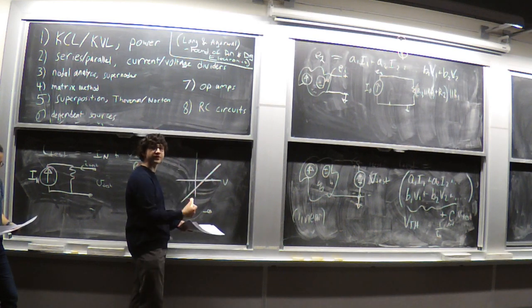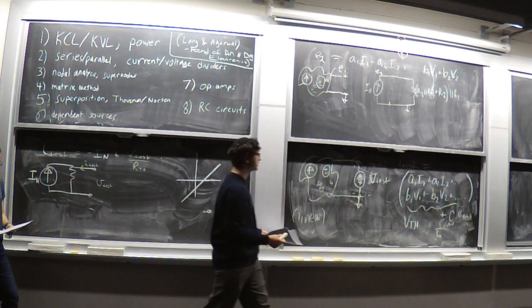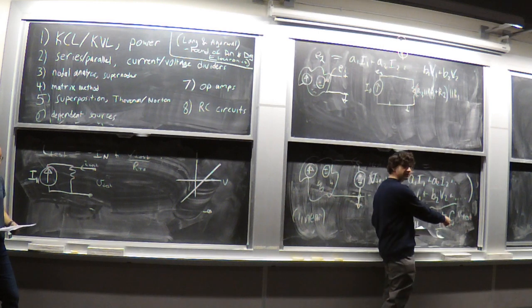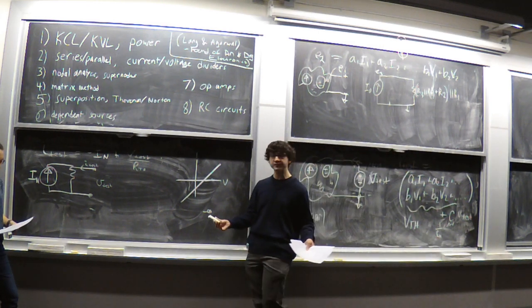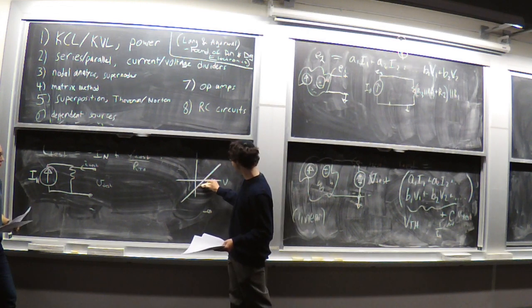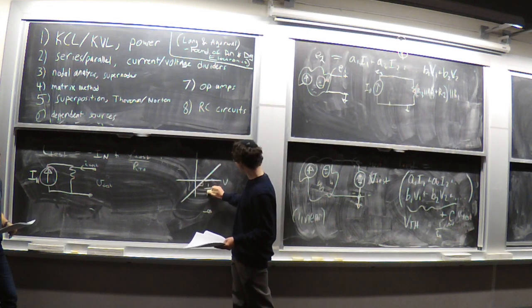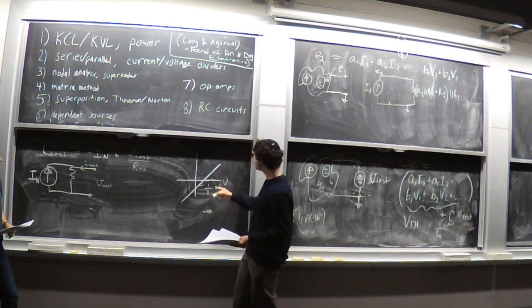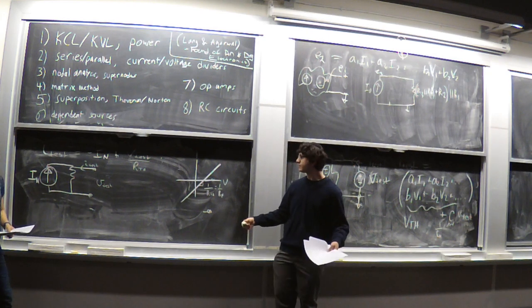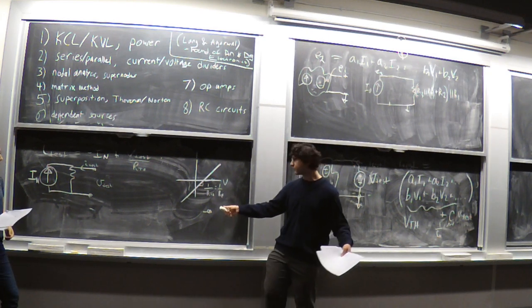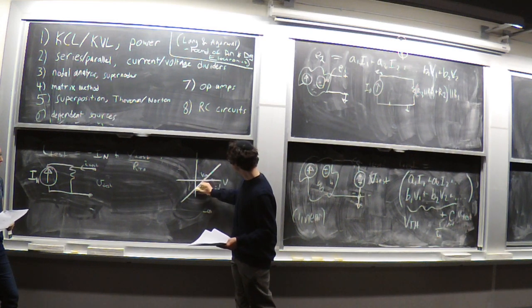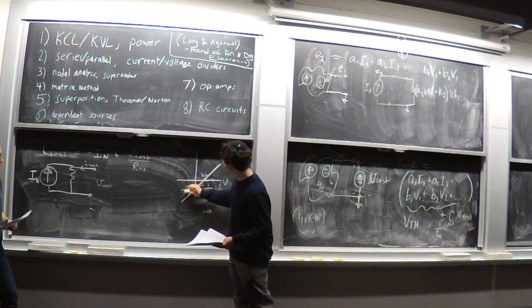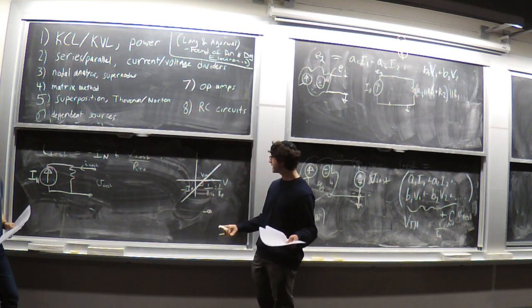If we look at the slope of this line, that essentially becomes this C value, right? That's the slope because that's how our I test and our V test were related to one another. Since this is I versus V, this slope is 1 over RTH and 1 over RN. And then the offsets from the origin have to do with V Thevenin and I Norton. So this intercept here is V Thevenin. This intercept here is minus IN. Very important to remember the minus sign.